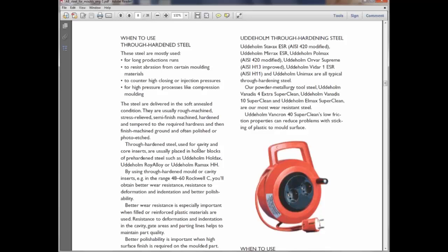Okay? 1 mm of extra material, and then we go for semi finishing. There we leave at least 0.2 mm of extra material for finishing purposes, 0.2 to 0.5 mm. It is somewhat of a range. We cannot say we have to leave only 0.2 or only 0.5. This is the range, 0.2 to 0.5 mm, that we leave for the finishing purpose.